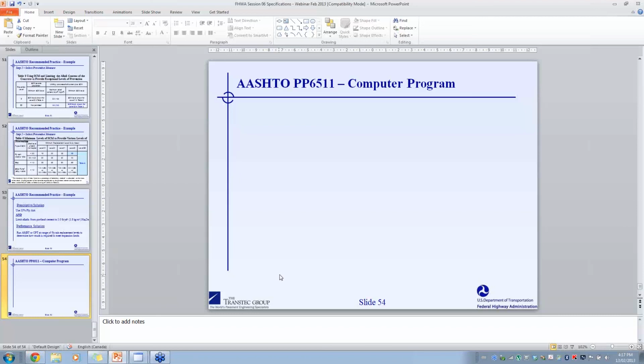Some people have shown almost a 10-fold increase very close to the surface, and you can get pop-outs occurring there because of the very enhanced alkali content at that surface. I think under those circumstances, yes, that is ASR. It's not a very frequent phenomenon at all, as far as I know. It's only confined to a few specific locations where they have certain aggregates. But in those situations, it is an ASR problem.